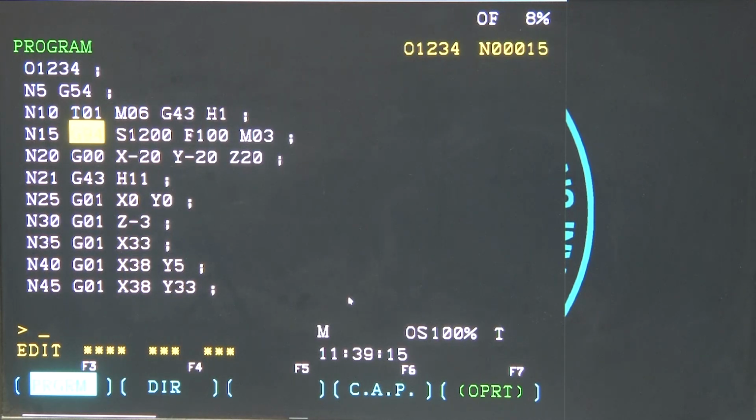Here this is the milling cutter. So, here the feed has to be taken in millimeter per minute. So, this is G94 and S1200, this stands for the RPM of the tool, okay. And the tool is 12 millimeter diameter, and for the aluminum we have selected, the RPM will be 1200, okay, revolutions per minute.